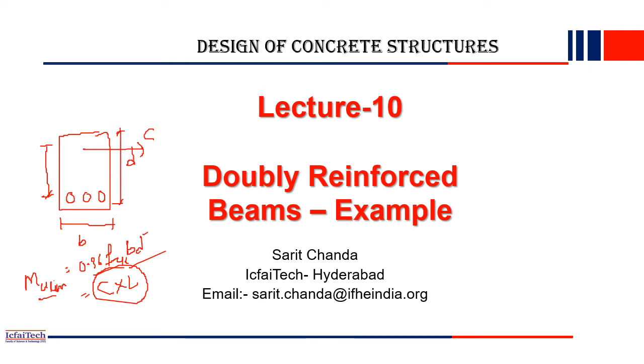Now, in a singly reinforced section, how do we increase the Mu lim? Suppose the load has suddenly increased on a beam, or a more intense UDL is acting on it. In that case, we have to increase the Mu lim of our structure. What are the options? In a singly reinforced section, if you increase the value of B or D, then we can increase Mu lim, since B and D are both multiplied. If both or either one increases, Mu lim will increase. This is one option.